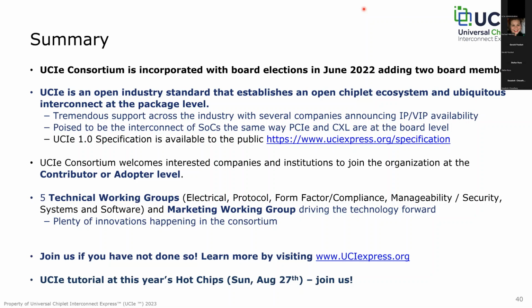There's signal integrity requirements due to channel differences and physical wire counts, not to mention by 16 versus by 64. So these differences are all intentional for optimization points for the different packaging technologies. Advanced package technologies are allowing you to get the maximum bandwidth densities possible,